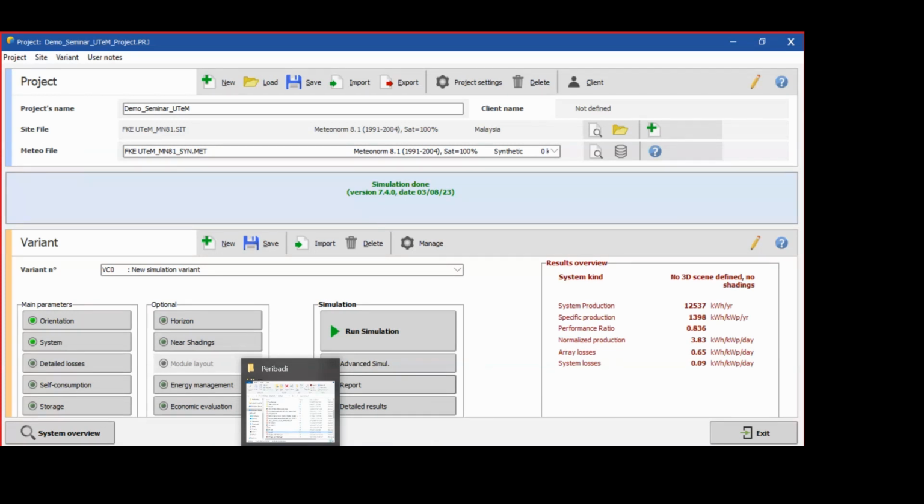Okay. Thank you. One important reason for having two MPPTs is to try to save more power from the PV loads. When we have two MPPTs, they operate separately. If the characteristics of the irradiance profile are the same, then they can track the same amount of power. But for example, if we have the modules on one MPPT in one direction, one orientation, the other MPPT we use for another set of PV modules at a different orientation.